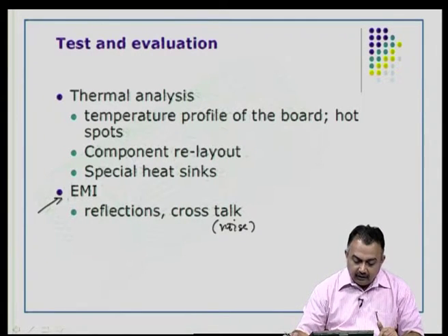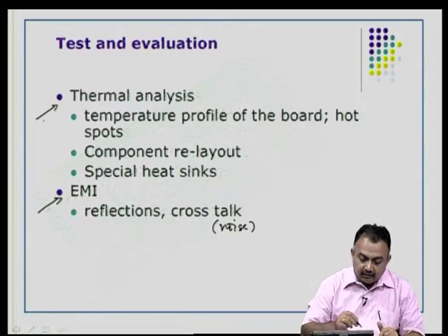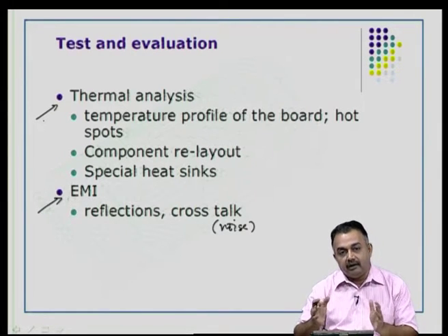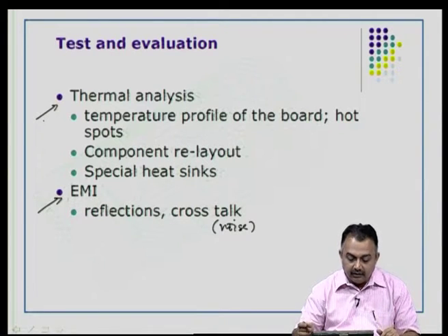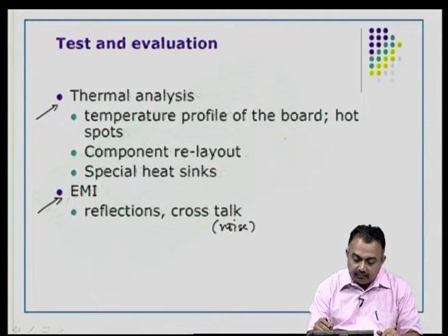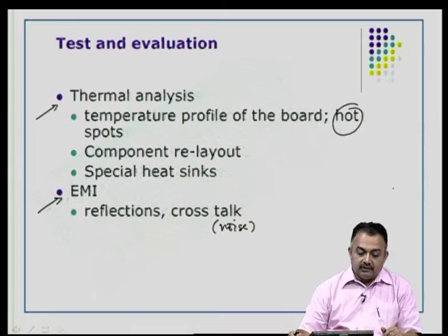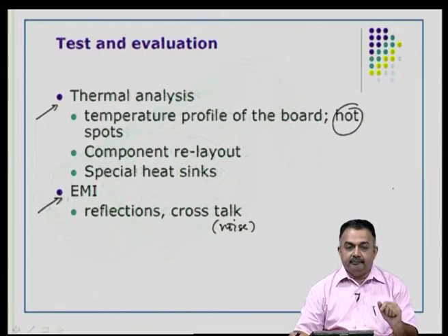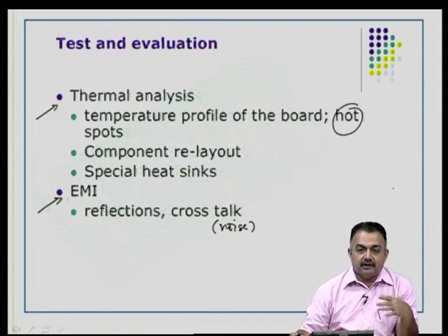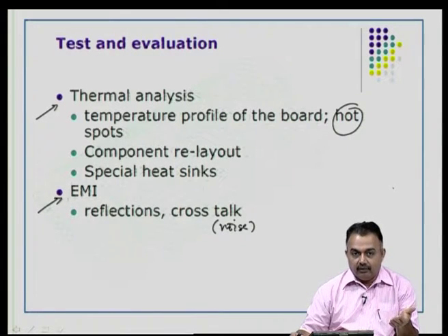Okay. Then the other important thing is thermal. Thermal analysis can be separately done using the layout details of your CAD program. Here you can check the temperature profile of the board and you can find out hot spots on your board. What do you mean by hot spots? These spots are danger areas because of heat dissipation problems caused by poor layout of your board.